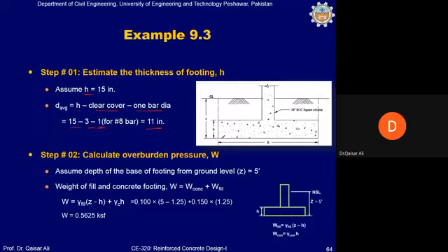Because there will be two bars placed here, one along one direction and the other along the other direction, if the diameter of this one bar is 1 inch, then 3 plus 1 inch, and we are taking d average. Because the d average will be used for the reinforcement calculation along both sides of the footing, instead of calculating reinforcement for each direction, because this will be just a waste of time and will not give us any meaningful information.